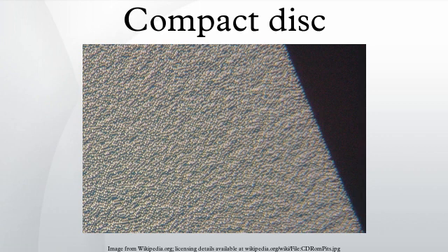Rewritable CD. CD-RW is a re-recordable medium that uses a metallic alloy instead of a dye. The write laser in this case is used to heat and alter the properties of the alloy, and hence change its reflectivity. A CD-RW does not have as great a difference in reflectivity as a pressed CD or a CD-R, and so many earlier CD audio players cannot read CD-RW discs, although most later CD audio players and standalone DVD players can. CD-RWs follow the Orange Book standard.